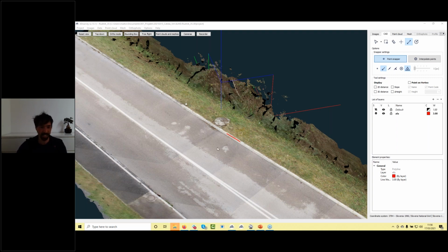Rudolf Borchin asks, how do I get the local elevation coordinate system into the program? Just support us with the geoid model, which you have in your GPS system. If you don't know where it is, the easiest way is to ask the person who sent you the GNSS instrument how you can get this geoid out of the instrument and send it to us. We will transform it to the 3D Survey file format, send it back to you, and give you the instructions on how to install it. It's actually pretty simple.